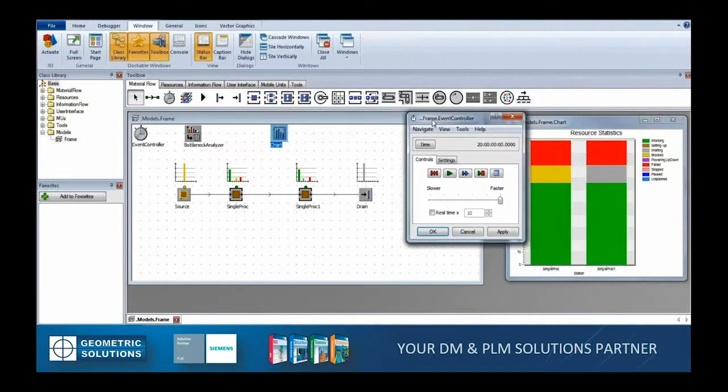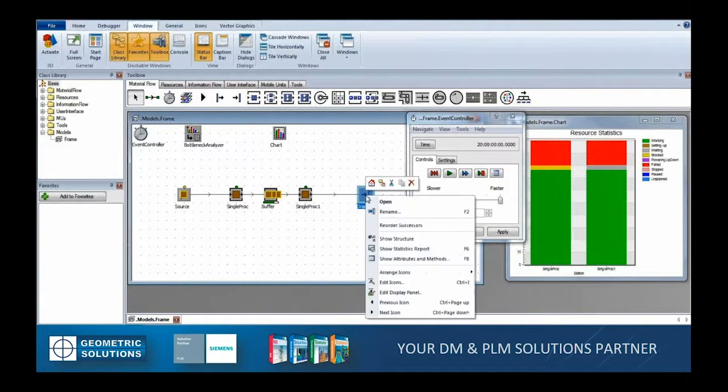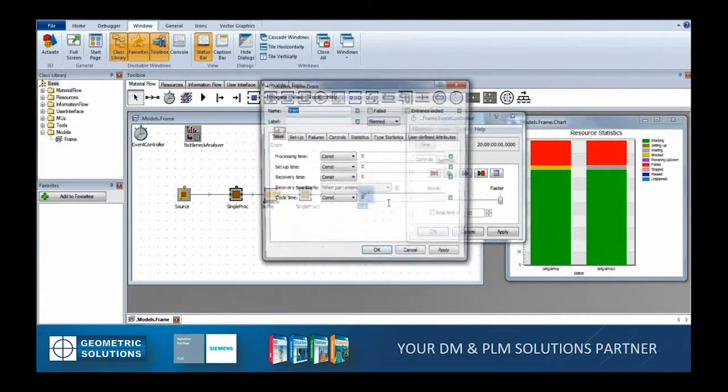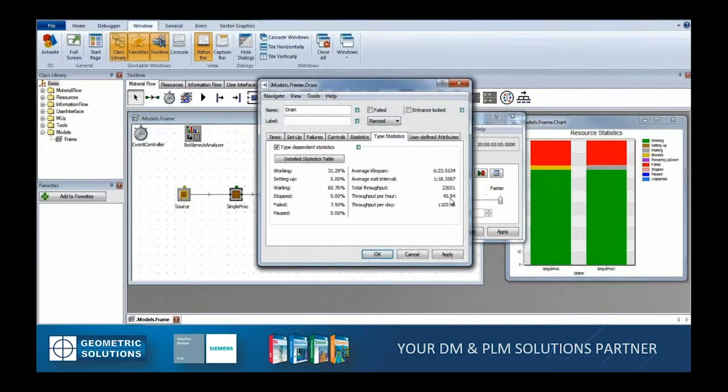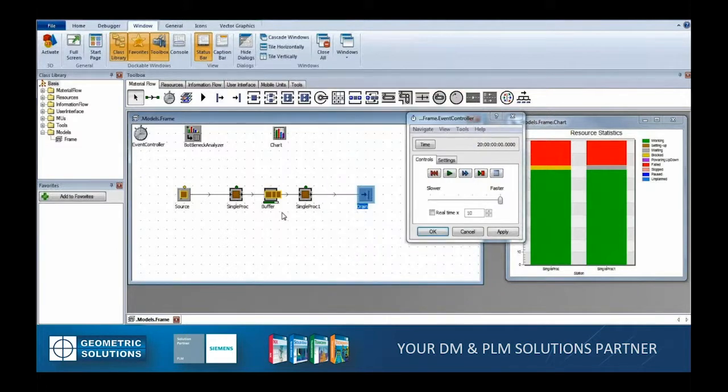So what I want to do is try to optimize that. Knowing that I have 20% downtime, how can I fix that? Well, a simple way is I'm going to put a buffer in the middle here. So I simply put a buffer in. I'm going to rerun my results, and you can see visually here, I'm much better. So I'm leading towards the right thing here. Looking at my throughput, I'm not at 48, I'm at 46 roughly. So how can I make that better?